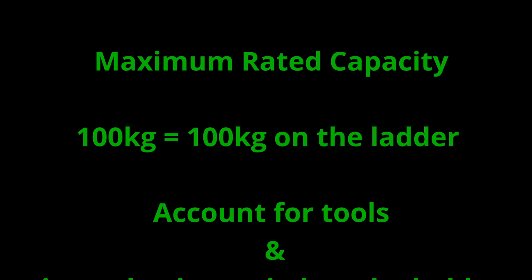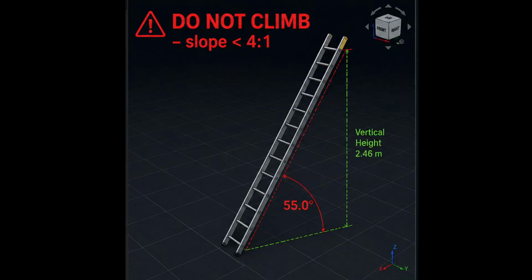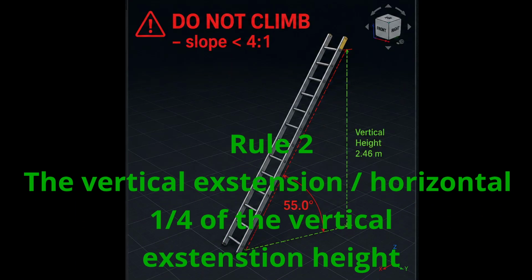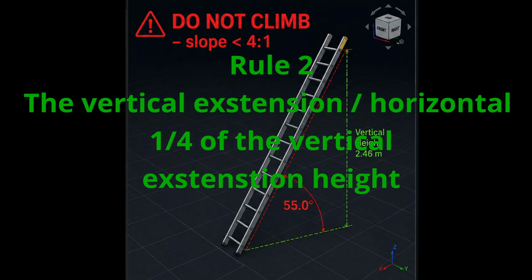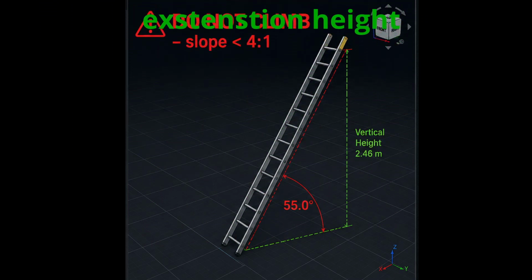You never exceed the maximum rated capacity of a ladder. The second, maintain a strict 4:1 ratio. The horizontal offset of the base should never exceed a quarter of the vertical extension height.